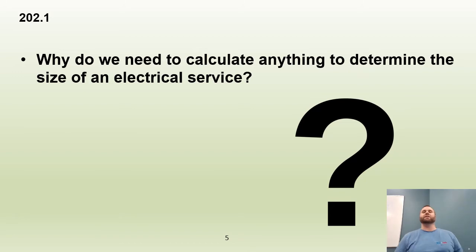Why do we need to calculate anything to determine the size of an electrical service? Well, think of it this way. Whenever we hook up a piece of equipment, whether it be a motor, a furnace, an oven, you name it, any kind of resistive or inductive capacitive load, we always size it based on its nameplate rating, telling us just how many amps it requires to run that equipment.